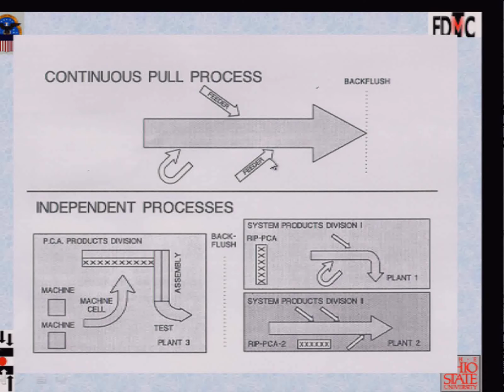And fundamentally, the sense is, look at your MRP system, look at the bill of material, look at the routings of all the components that have to be made that are not basically hardware items which you're purchasing. Replace those components with the routings. You will get something called the indented bill of routing. It's essentially what we call the operations process chart. And then use the operations process chart to essentially create the value network map. And then with the value network map, design the layout and schedule the facility.